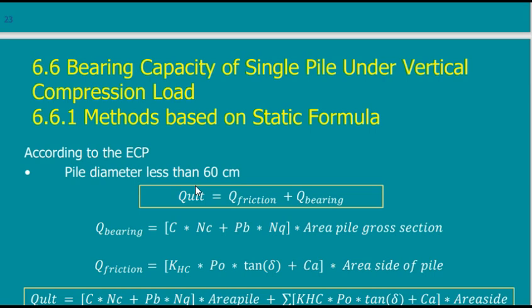So this is the exact, this is 100% correct. And I compare this to my design. If it is less than my design, then it is unsafe and I have to increase the number of piles. If it is more, I will not take the more. I will take only what I have designed. This is my rule. So this is what we mean.